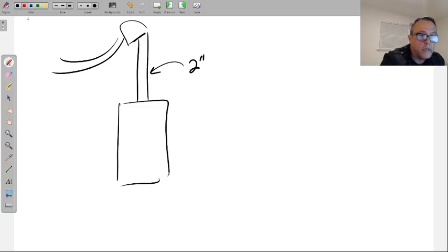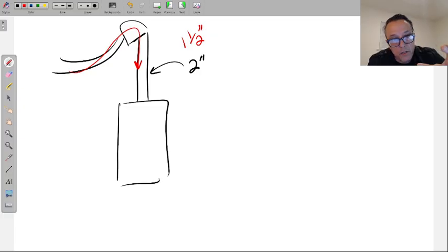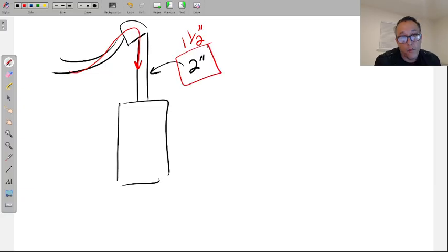Even though, if I use the code book, for the wires that I was putting in this conduit, the conduit only needed to be 1.5 inches. So the code book was allowing me to put a smaller conduit based off of the code book, but the county or authority having jurisdiction supersedes that. So always remember that. Won't come up in your electrical career just yet, but something to consider.